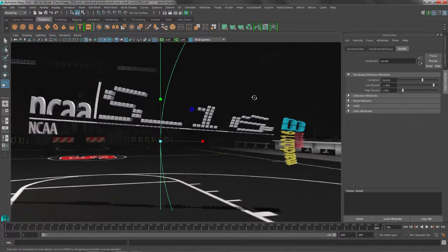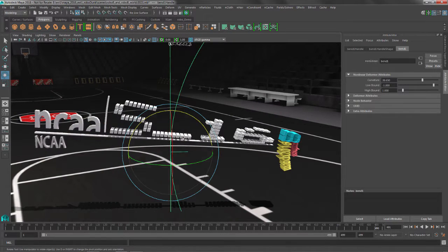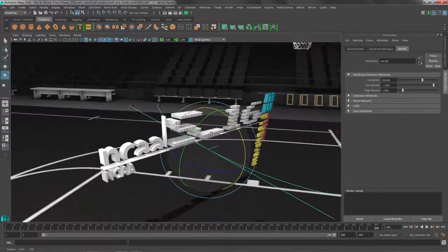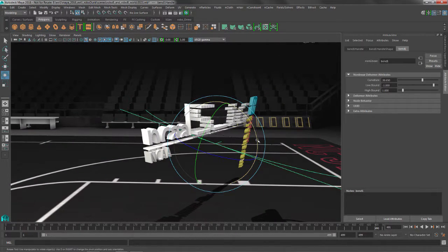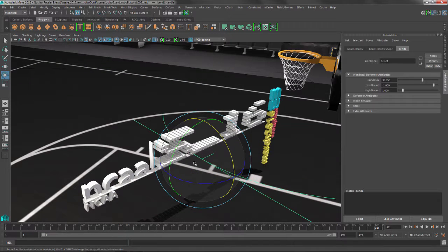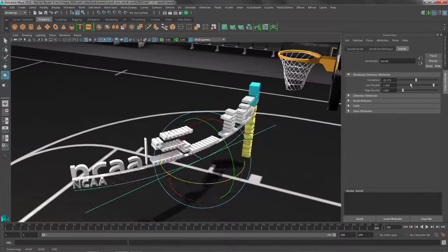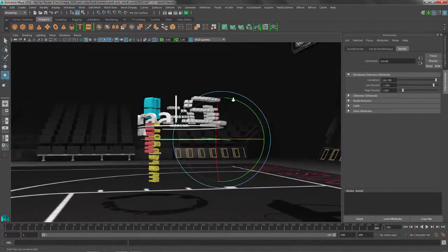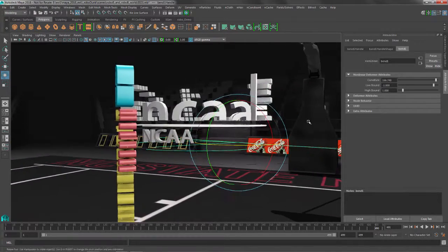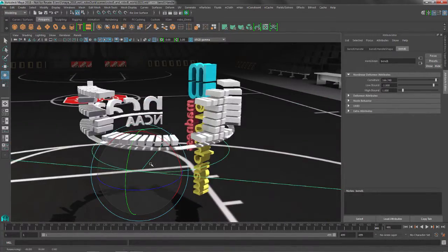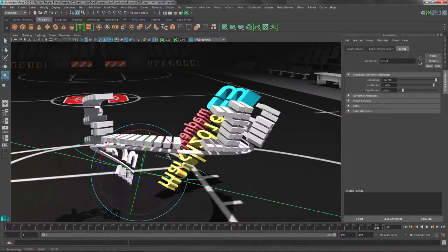Now, obviously, objects can pass through these nonlinears, and these nonlinears can be positioned and rotated. So what we're going to do is hold down our J key to spin that guy around, something like that. Oops, I got to get one more snap on that guy. And then we're going to spin it around so that it's going down the length of that line. And I can use this nonlinear deformer to do some fun stuff with this. So if we wanted to have the animation of the camera spinning around this guy, you can do something like that. Obviously, you can take the nonlinear and tweak it out and do some really cool effects with it.